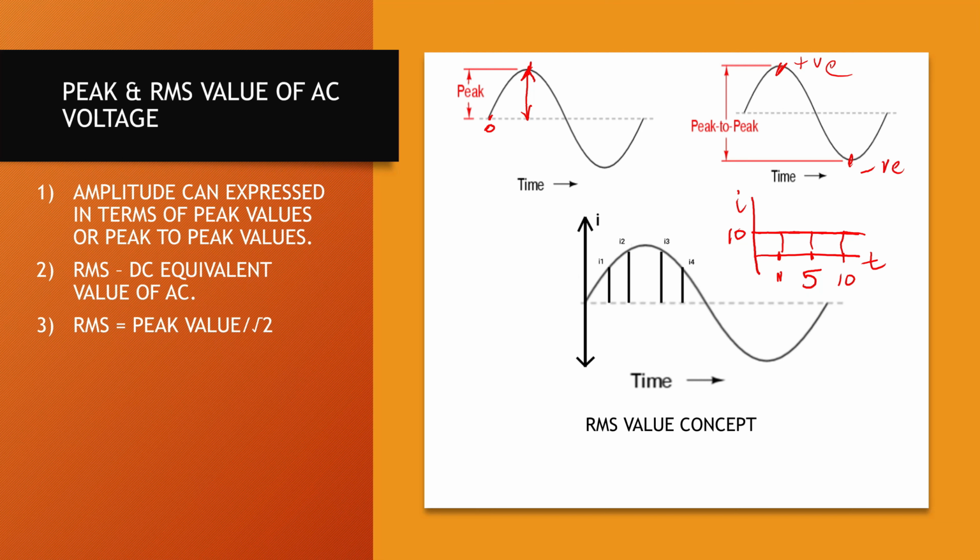Is this true for AC? Of course not. Because if you see in this diagram over here, you basically have some different value of current for some time. For some time the current value changes again over here, and current value actually changes again over here. So how do we actually find, let's say, the power consumed by a bulb when there is AC voltage? So then the idea comes about RMS, which is root mean square voltage, and we'll see why this is called root mean square voltage.